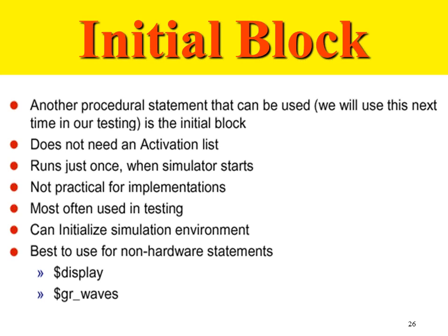Another thing we can use the initial block for is whenever you have big memories in the design. Somebody mentioned this. We always have to initialize the registers. Internal memories are registers. So the memory has to be initialized. All the bits of the memory have to be initialized to 0 or 1, so they don't start from Z value or tri-state value. So that's another thing you can do. Anything that you want to do once when the hardware starts, because ultimately this will generate hardware for you, you can put in the initial block. That has to run once.